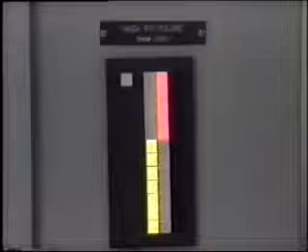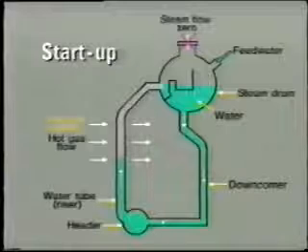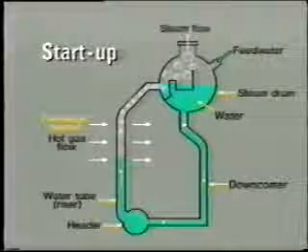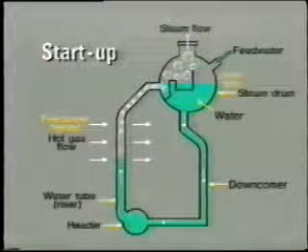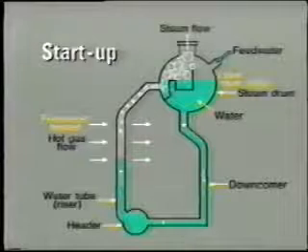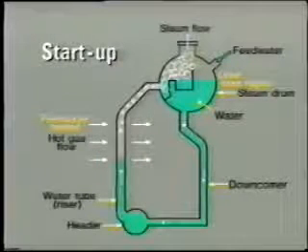However, under the minor fluctuations which take place during normal operation, the three elements operate together to provide very stable control of water level. The phenomenon of water swell, that is, raising of water level, occurs during startup of the HRSG. In this case, as the water is heated and pressure is raised, more and more steam bubbles are formed within the risers, with the result that the water level in the drum rises. This increase in level can be considerable, especially if pressure is being raised rapidly.